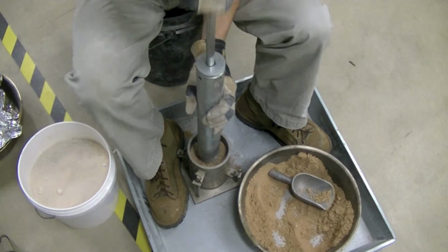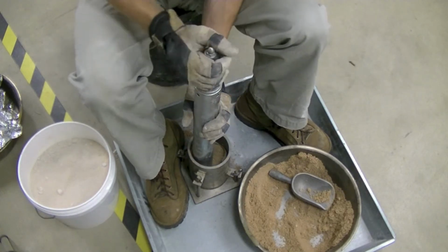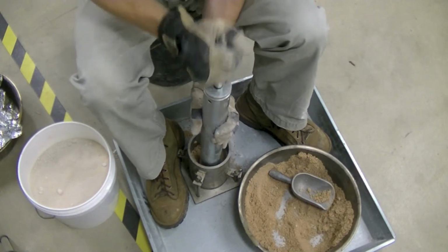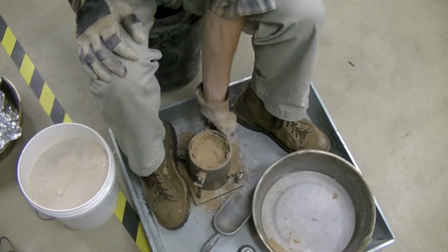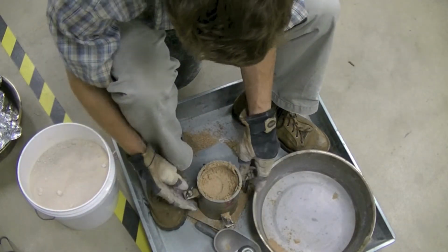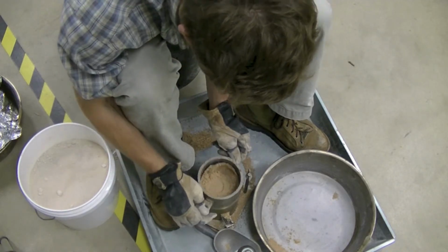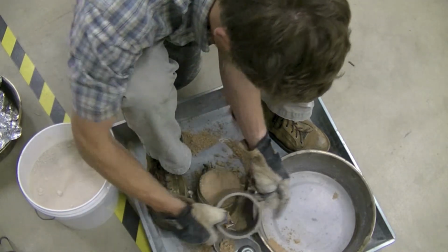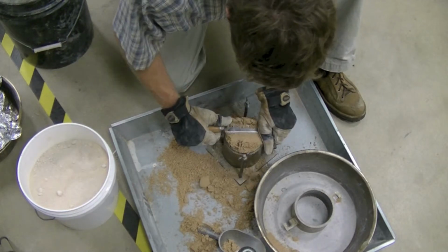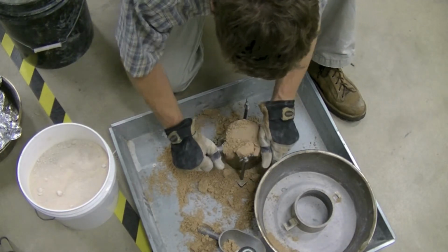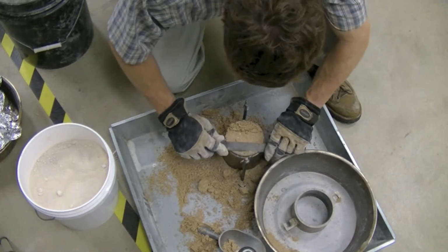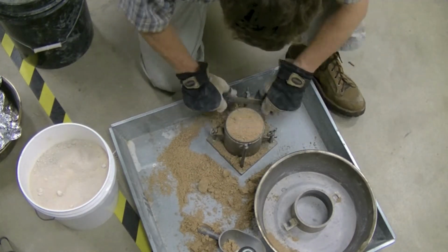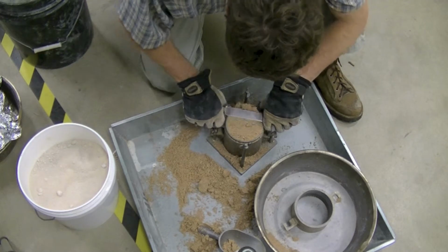After the 3rd lift, the soil should be at a level above the top of the mold if it did not have its collar on. Carefully unscrew the wing nuts and rotate the collar back and forth, being careful not to shear any soil off. Remove the collar, place the straight edge against the top of the mold and begin a sawing motion, cutting any soil that has been compacted above the top of the mold. Clean off the top of the mold, ensuring that the soil is flush with the top.